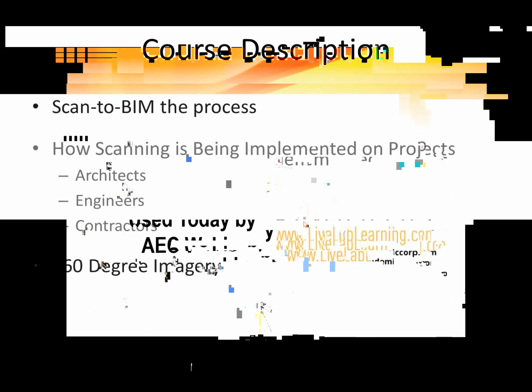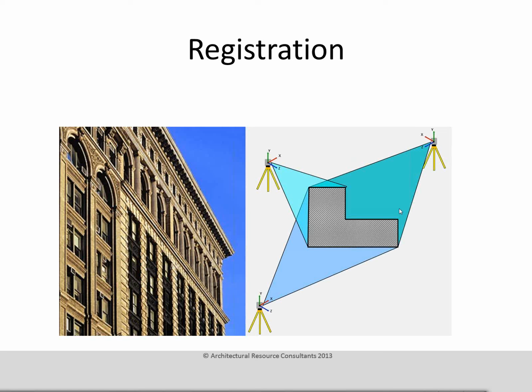Ideally, you want to have overlap in your scans between scan 1 and scan 2. These two scans over here don't have overlap, so I'd probably drop another scan over here to get that overlap.